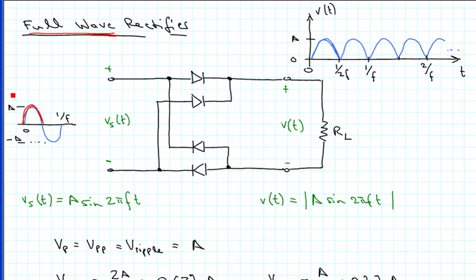So during the positive half cycle, we have current flowing here through this diode, and then it flows through the load resistance here, and it flows back through the diode down here, and then out through the transformer winding or the battery. That would be here at the input or anything similar.